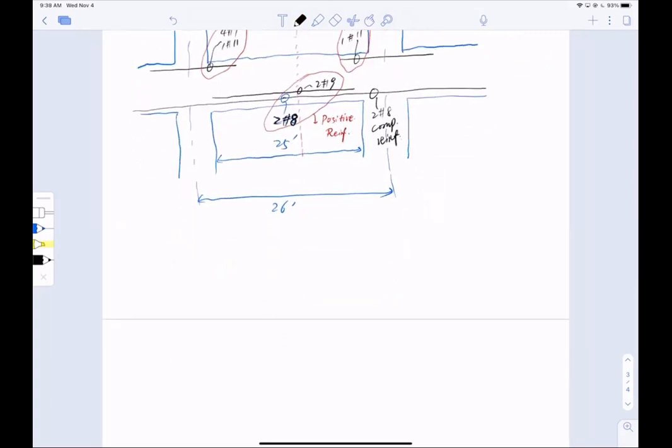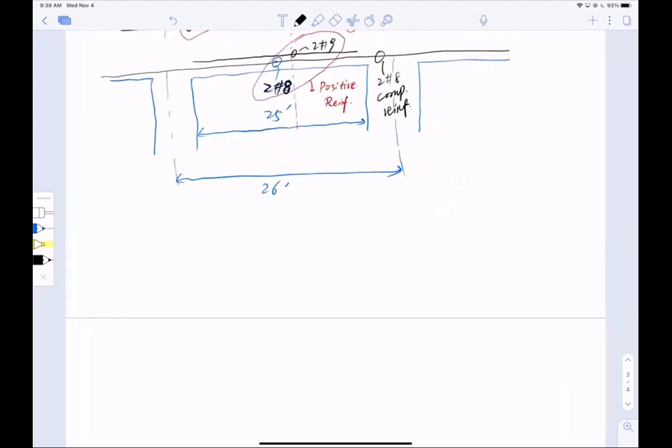Okay, so what does the moment look like? For the sake of time, we're just going to show you the moment diagram. So now, let me simplify the structure. I say, look, cut it here from clear span to clear span, and then I have a beam. And now I draw the moment diagram, and this is parabolic. I try my best to draw a parabola. It's a little bit shaky, but looks pretty good.